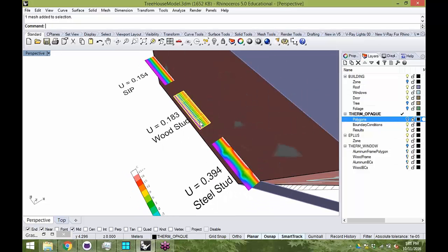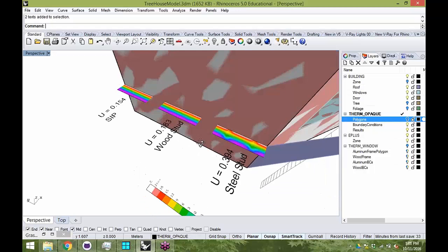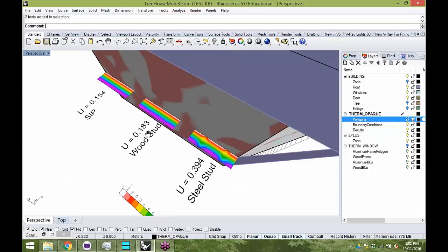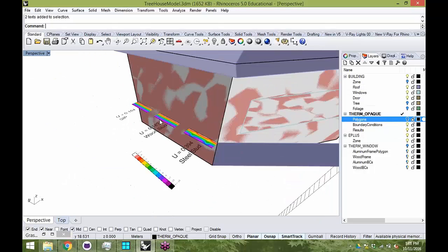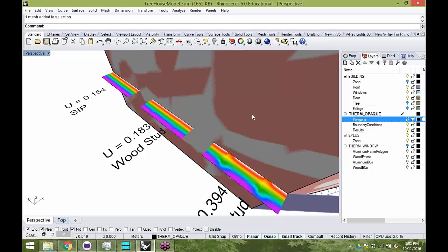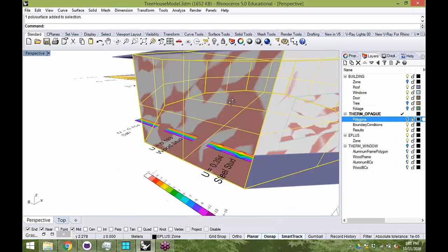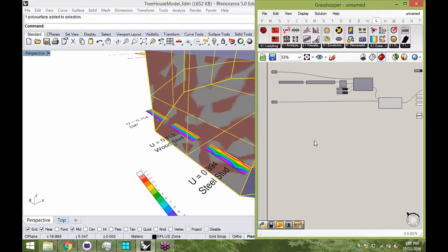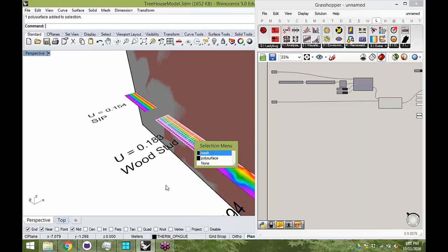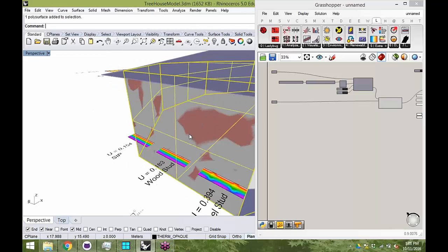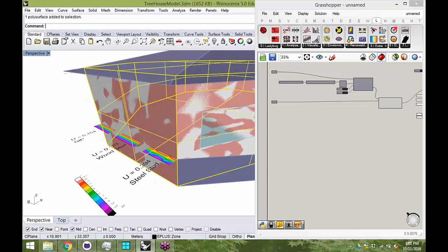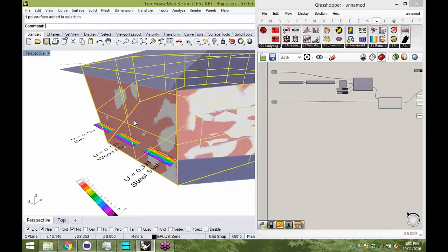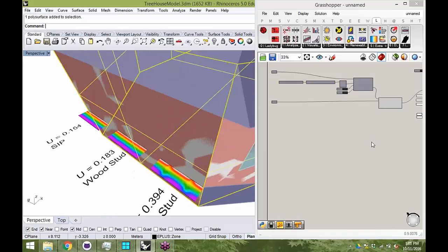I think this is a decent U value, or at least one of the best that we're going to get for our 8 inches of insulation. All right, so now let's take the results of this and work that into our full building energy model. The first thing we have to do is build up all the mass of this construction. The thermal mass matters a lot to the energy simulation precisely because it's dynamic, and because the thermal lag can end up affecting the results quite a lot.